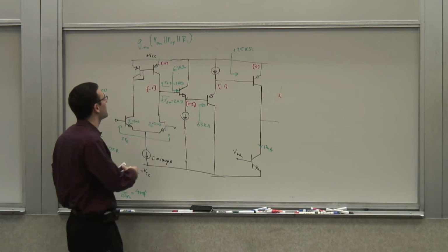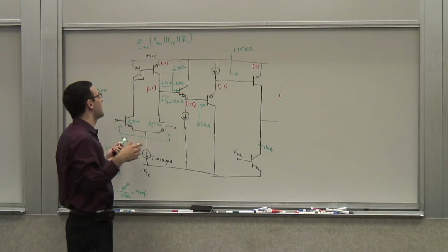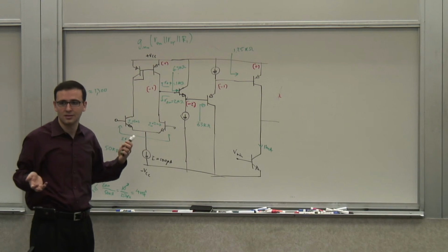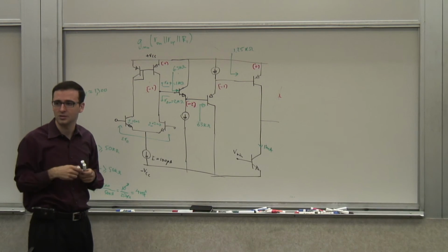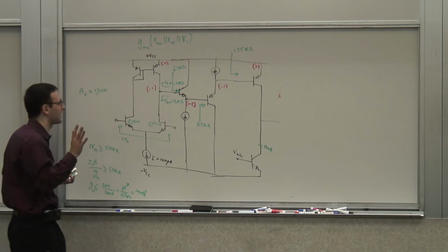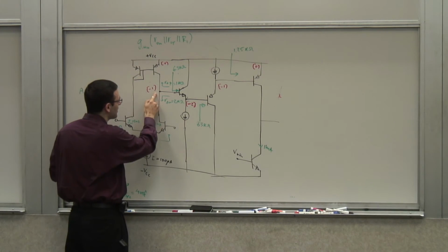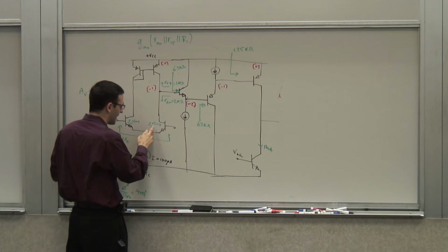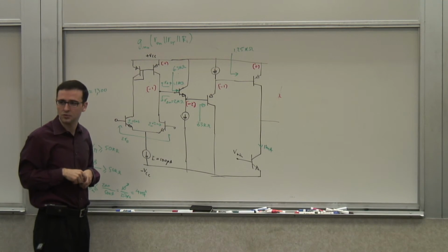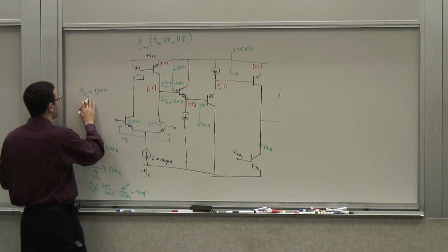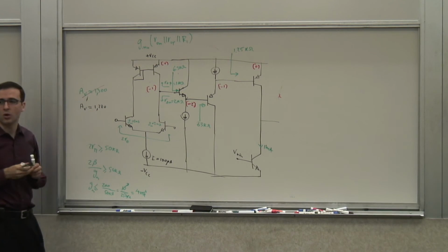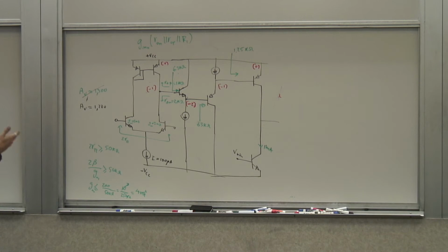So I have to calculate that parallel combination, so whatever that is. It's probably going to be around 600 kiloohms, right? It used to be 670, but now because of the 6 meg, I would say it's approximately 600 kiloohms. You can do it exactly if you want. It's going to be in that ballpark. So the total impedance on this node is 600 kilo ohm, multiplied by GM of 2 millisiemens. So that gives me a gain of approximately, so 81 is now approximately 1200, which is good. I didn't lose a whole lot. This is an approximate calculation. Okay, so I'm okay for the first stage.